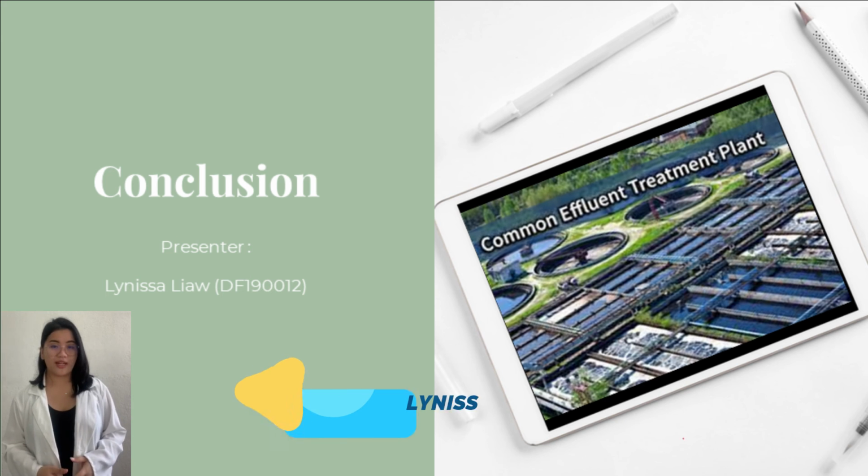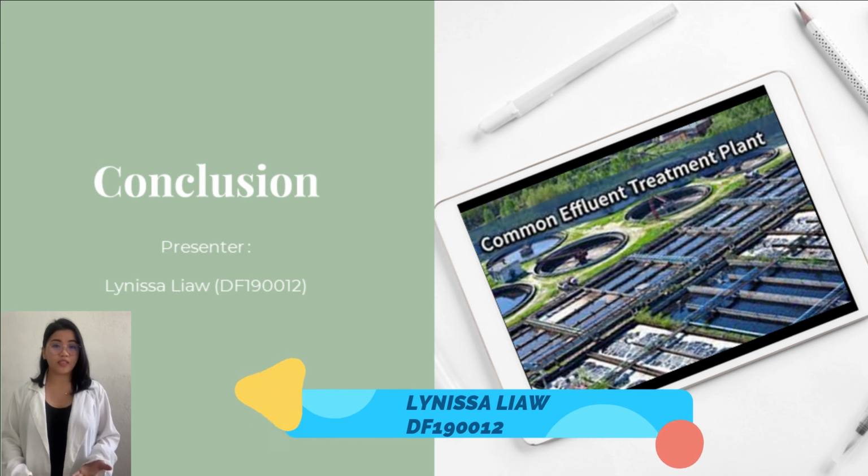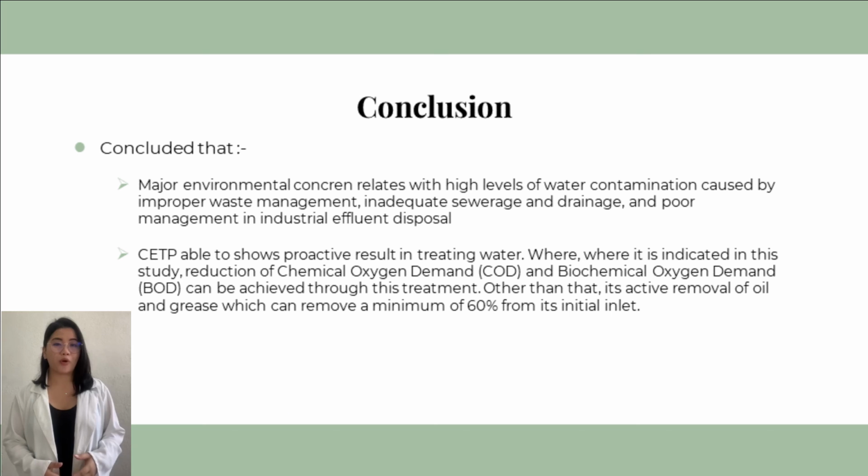For the overall conclusion, the main environmental concern is always related to high levels of water contamination caused by improper waste management, inadequate sewerage and drainage, and poor management in industrial effluent disposal. In this case study, we have chosen the common effluent treatment plant, CETP, because of its durability in its own way. For instance, efficient reduction in parameters, where it is indicated in the study, reduction of chemical oxygen demand, COD, and biochemical oxygen demand, BOD, can be achieved through this treatment.